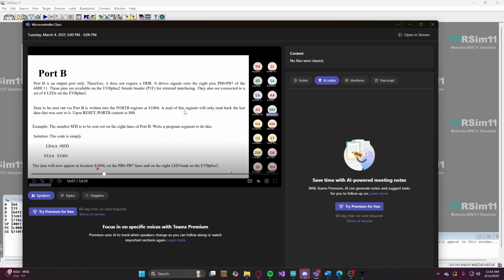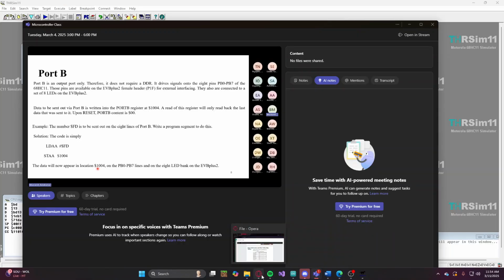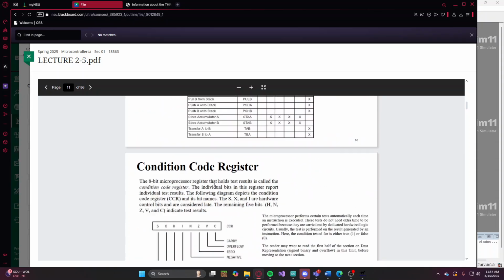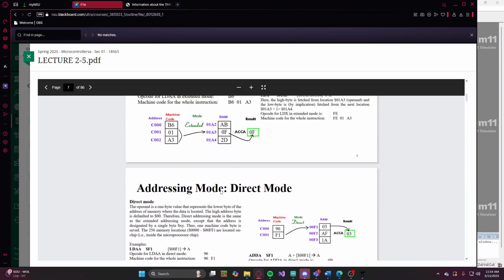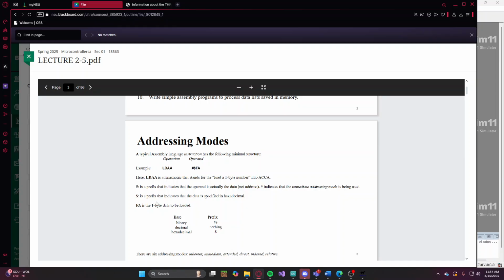On default, the content in 1004 is $0. Looking at it, I believe that's hexadecimal. Yes, so on its own, port B stores hexadecimal values, and it's saying that on default, it's storing the two-digit hexadecimal value 00, which is just 0.